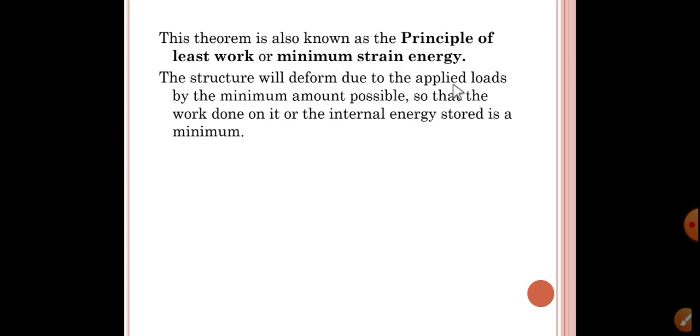The structure will deform due to the applied load by the minimum amount possible, so that the work done on it, or the internal energy stored, is minimum, right? So, dear students, these two methods are important for finding out the slope and deflection, and they are even used to analyze indeterminate structures, right?